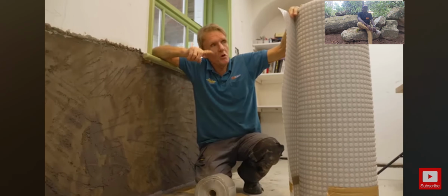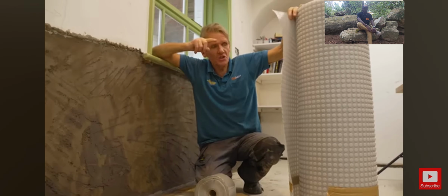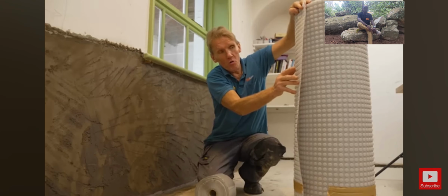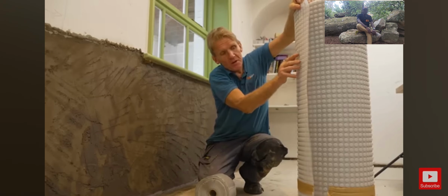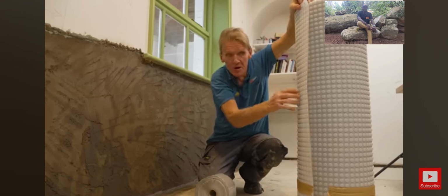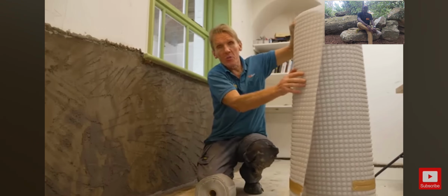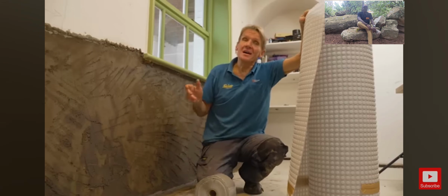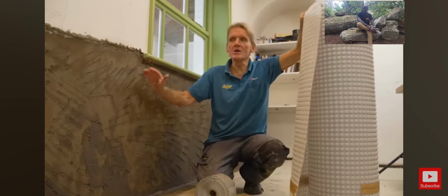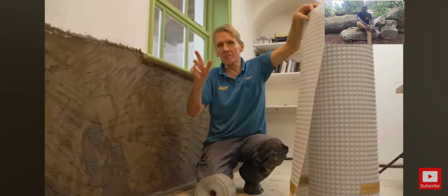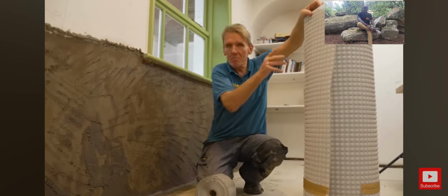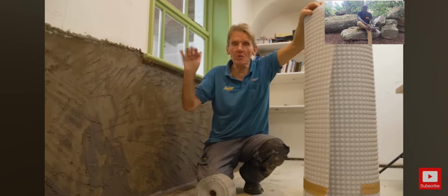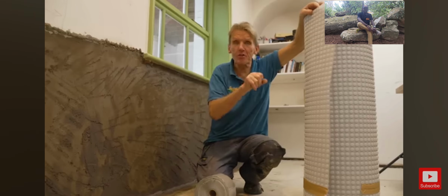Now, while I'm here, I just want to talk about another product in the Safeguard range, which is this plaster mesh tanking membrane, and this is a low profile one. You may have seen this before with the bigger studs, but the idea is that you've formed a cavity behind it for the water to drain down behind the membrane, and what you then do is you have a channel along the floor which collects the moisture and takes it away to a pump. So if you've got major problems with water penetration in a basement, you may be better looking at a membrane as opposed to a tanking slurry. But the best thing to do is talk to Safeguard, tell them what you've got, and they will recommend the right product for your job.